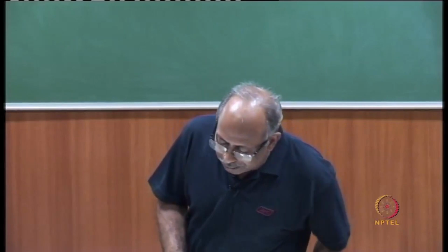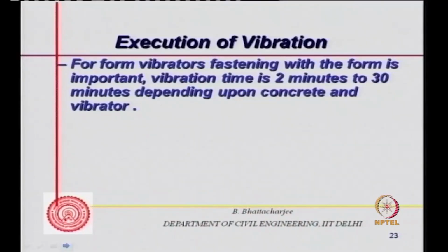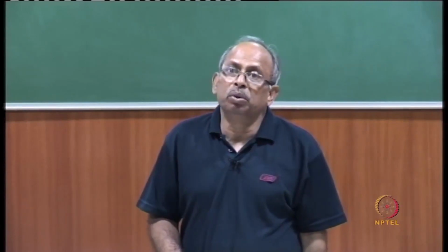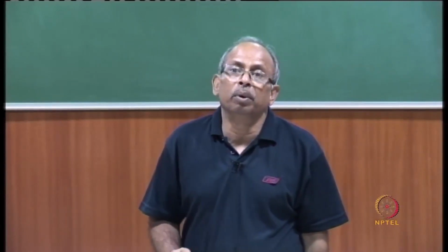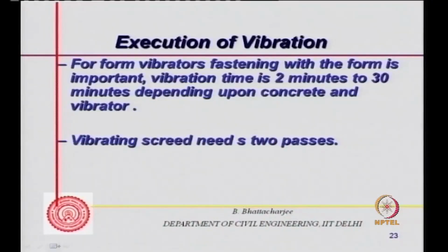For, of course, shutter vibrators, which are fastened with the form, vibration time is 2 minutes to 30 minutes depending upon concrete and vibrator itself. So they require a longer period of time, more energy. Screeds need, of course, 2 passes.